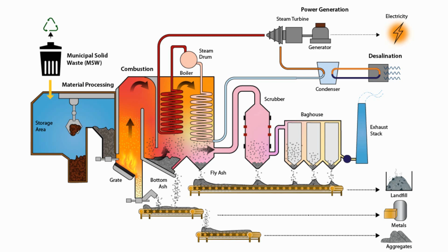What happens next really does depend on what we're burning. With biomass, we can guess the moisture content, the ash content, the sulfur content, and all of these kinds of things based on the material that's being delivered. In a waste-to-energy plant, we can't really do this. We don't know what the sulfur content of the waste is, or the ash content, or the moisture content, or even the heat value. Because of this, it's quite tricky to design a boiler that's suitable to burn waste.